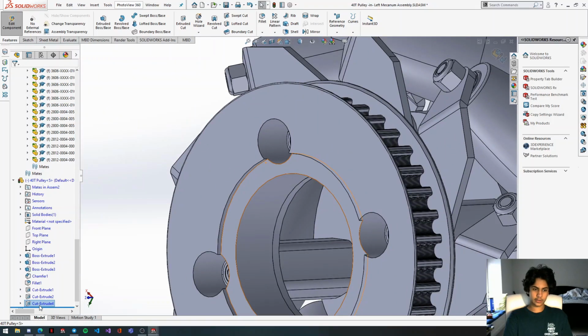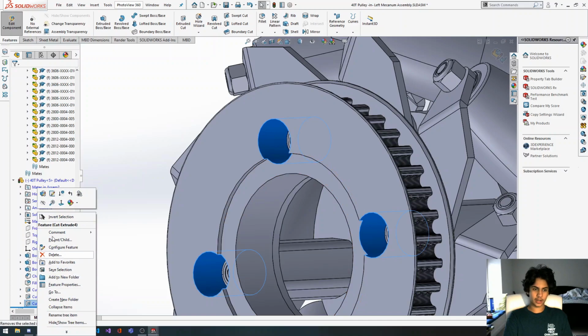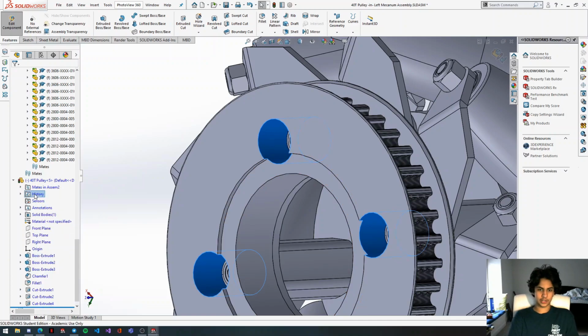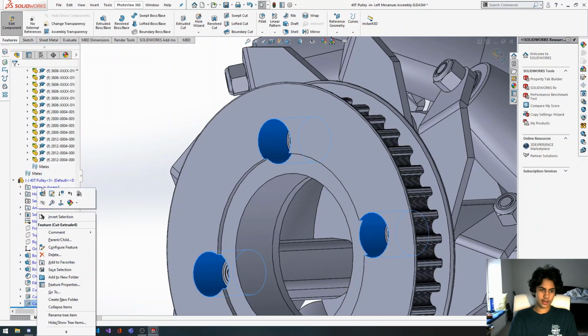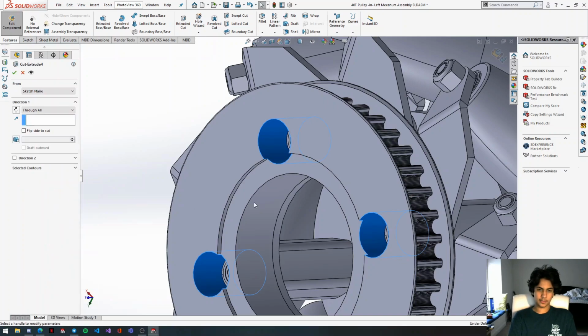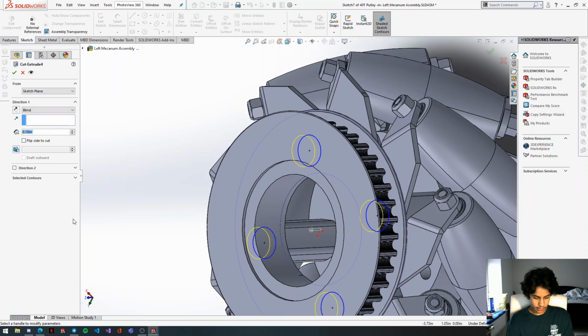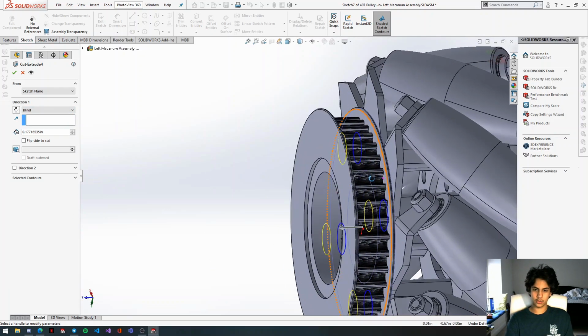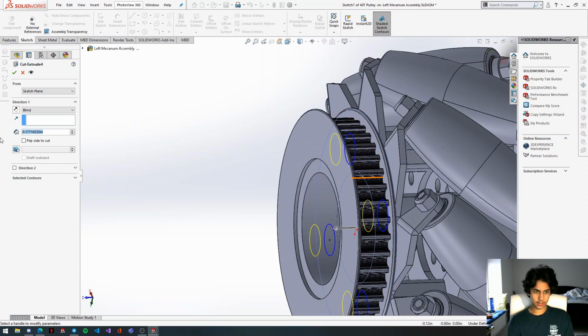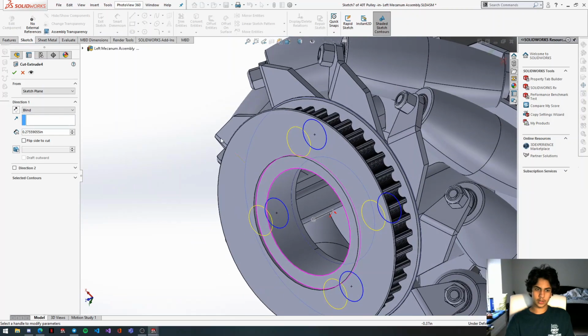So what I'm actually going to do is right-click this extruded cut, and you can see Edit Feature. Oops, selected the wrong thing. We're going to right-click Extruded Cut and click Edit Feature. And then instead of selecting through all, you can do blind, and then maybe do 4.5 millimeters, so it goes pretty much halfway through. Or you can go for maybe 7 millimeters. That's probably the better option. So we're going to do 7 millimeters. We're going to hit the check mark.